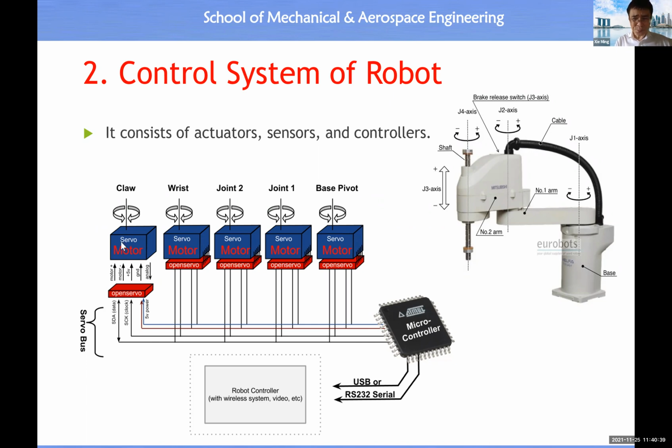At least the control system must provide the capability to control joints 1, 2, 3 and 4. Then you may have an additional one for the control of the hand, maybe a gripper. So the control system must have the capability of controlling 5 axes. The last one is for the degree of freedom of the hand. The arm manipulator itself has 4 degrees of freedom.